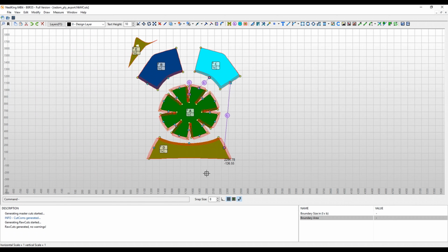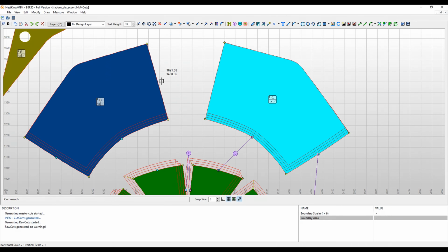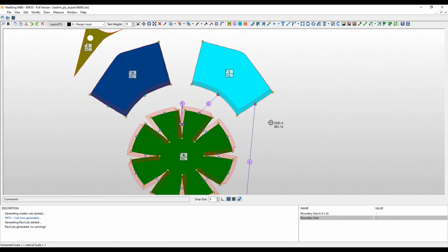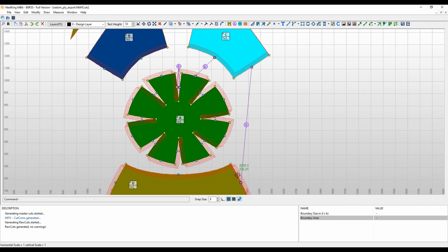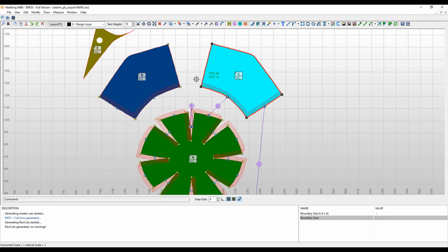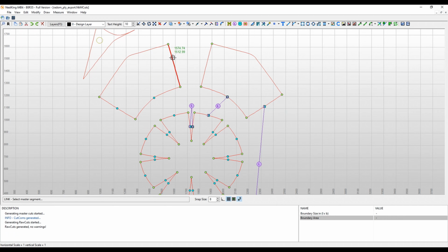So this looks good. We also need a link here. We could either choose to use one of the masters and slave conditions from other links to reproduce on this one. But actually here in the middle, I would like a change. I would like to offset in both directions just to remain balanced.